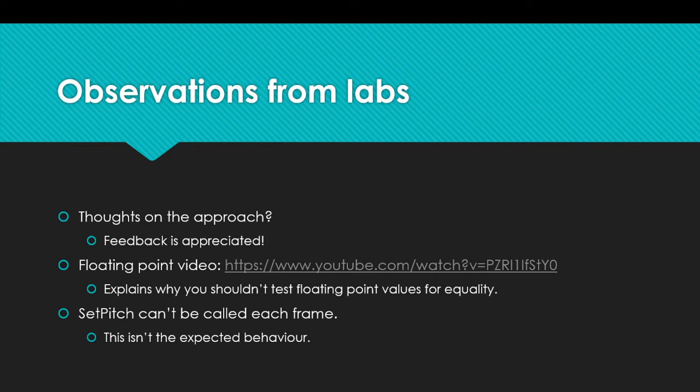A couple of bugs we saw in the labs last week were related to floating point. Floating point is slightly counterintuitive, and I think this video here does a good job in explaining why. But what it really boils down to is that you can't do equality checks on floating point numbers, so you can't say if this floating point number is equal to 0, and it's because of the way that the floating point value is represented in the hardware, as this video will explain. So just have a look at that, and remember that if you're using floating points, you're usually checking if they're higher or lower than a value, and not if they're exactly a value.